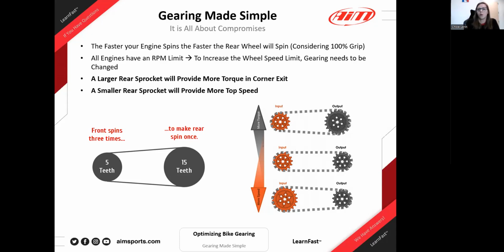And we call that a longer gearing. You're going to be staying longer in your gear when you're on a straight line. And it's always a balance, right? You want to accelerate well, obviously, but you also don't want to run out of speed at the end of a straightaway, right? So getting the gearing correct for a track is an important part to balance out the acceleration zones versus maintaining or being very fast at the end of the longer straightaways.